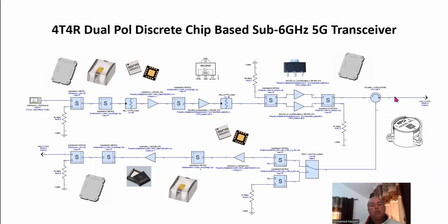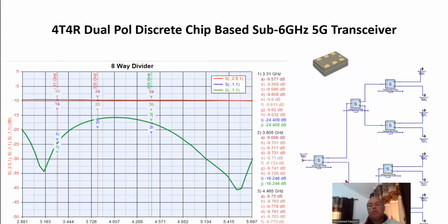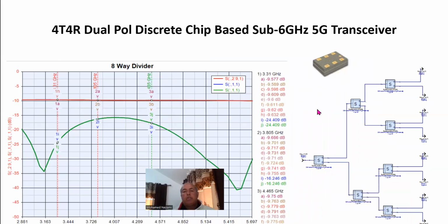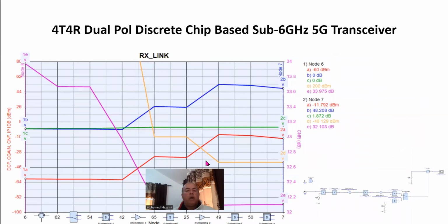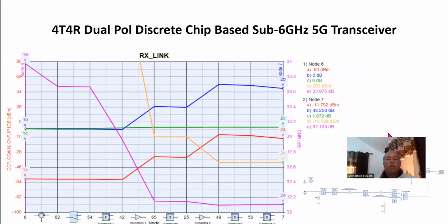So I look at this, and now you need to realize this in actual chips. These chips have a lot of associated passives, and there's a lot of copper traces connecting them. So really, what you see when we looked at the transmit receive, this is the passive distribution network for the 4. When we looked at the performance of the chain, the link budget of this chain, we really didn't account for all of that stuff.